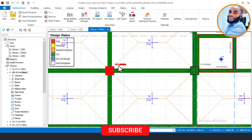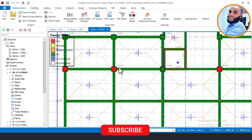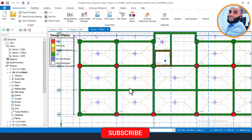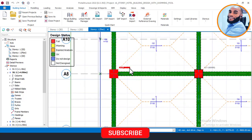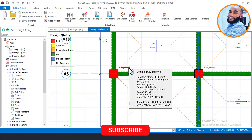Most of the columns are showing green and then some are showing red. So these red ones are the ones that fail. Let's begin to check why they are failing. To check why your column is failing, click on the column, right click, and then click on the place that says section design.